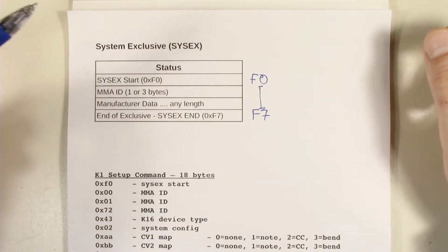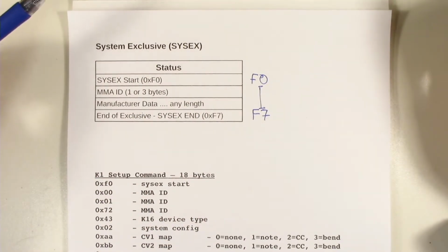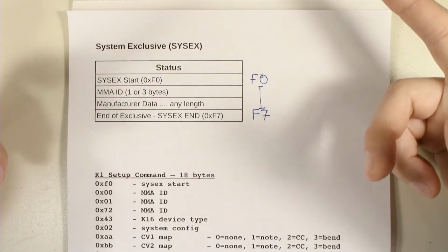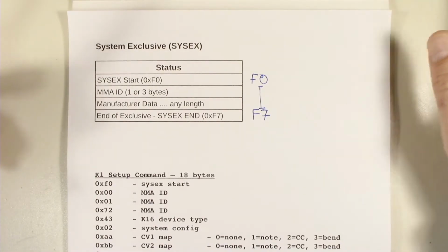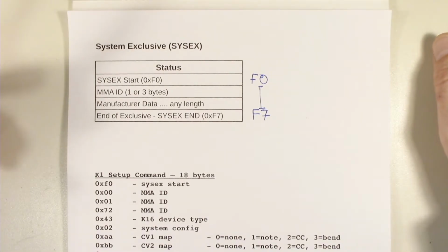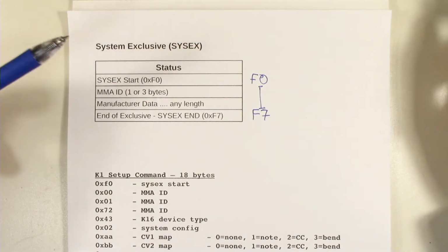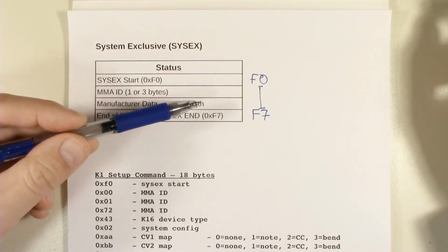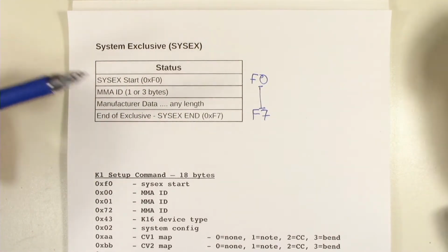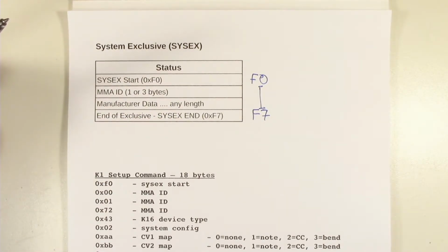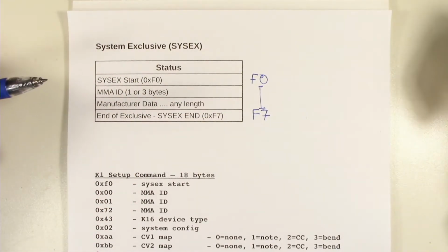You can pack the data and rotate around and fill all the 7 bits with all the bits of the bytes, and then move over one. I've done other methods where I just use the lower 4 bits and send a byte over 2 bytes on the wire. That's a little less efficient, but it doesn't really matter in some cases. So there's all kinds of different ways that you can decide how to send the data that you care about. The other way is you can just encode your data in a format that will just fit directly on the wire without any funny encoding.